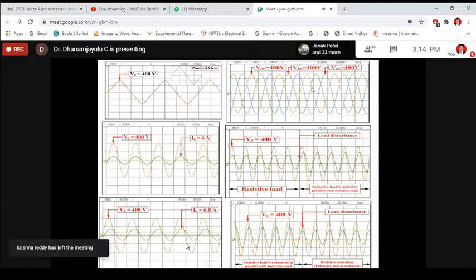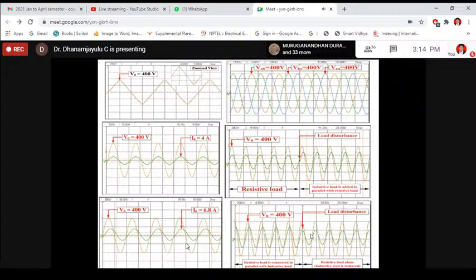This is the 3-phase 19 level output voltage waveform, and this is phase leg A with linear load, with resistive load, and again motor load, which is nothing but an inductor load. Again, we have tested with the linear load, that is R load to L load, and L load to R load. During these dynamic load changes, the proposed inverter is well stable.